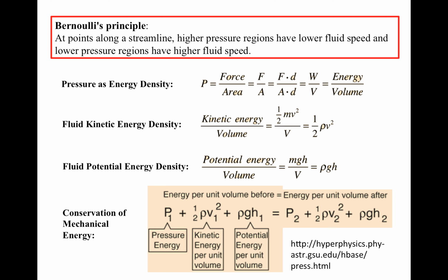There is also a different perspective for understanding Bernoulli's equation, which is based on the conservation of mechanical energy. We are probably familiar with kinetic energy and potential energy, but may not be familiar with pressure energy. In fact, pressure can be considered as the density of the pressure energy. In the simplest form, pressure is just force divided by area.